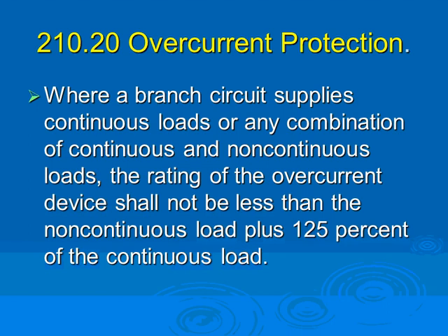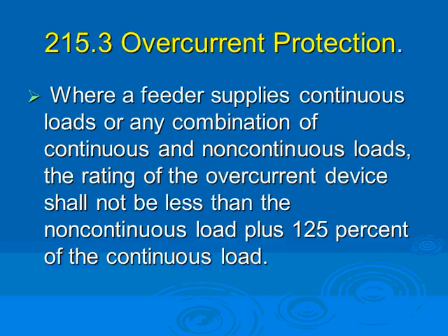So out of a 100 amp circuit breaker, I can pull 80 amps continuous, and the other 20% leftover is not sitting there doing nothing. I can pull it as non-continuous, right? So receptacles, they're energized, I took the 20 amps for 2 hours and then off, not 3 hours. Some people think if it's 80% of the circuit breaker, the other 20 are doing nothing. They are feeding the non-continuous load, but they turn them off. They don't operate for more than 3 hours. So that's a big deal when it comes to sizing the overcurrent protection device.